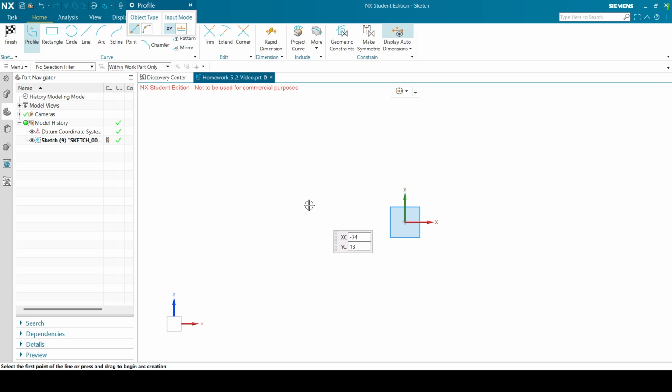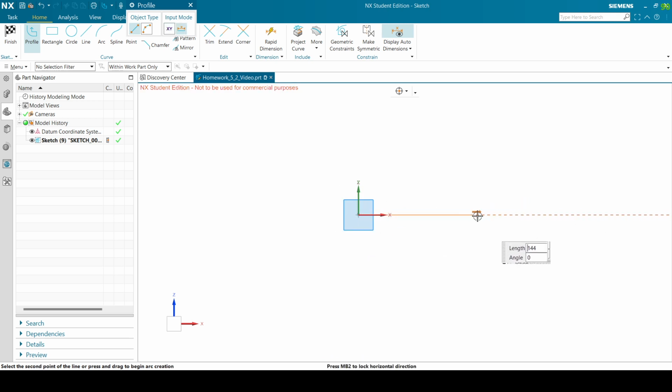First I'm going to start with the outer profile. You will see in a moment, I'm not going to add the entire straight line. I'm going to add a section and then another section, and I'll discuss why a bit later. So first I'm going to add this one, then this one, add my little arc over here. I don't want to add any constraints; I'm just going to make sure none of these lines show up that indicate constraints.